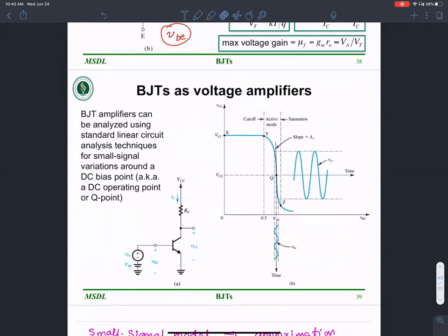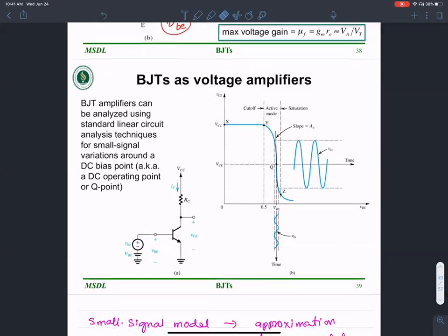Not only is there a gain, the gain is also inverted, owing to the fact that the transfer curve has a slope that's not 1. Okay, that's negative. It has an inverse slope. It has a negative slope. The transfer curve has an inverse slope, and the slope represents the gain at that point. Okay, so when the slope represents the gain, the inverse negative slope means that there is an inverting amplification going on here.